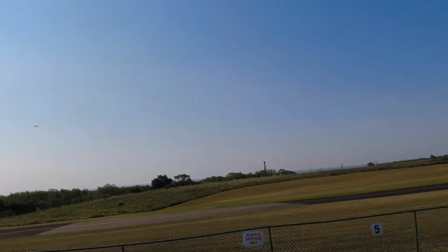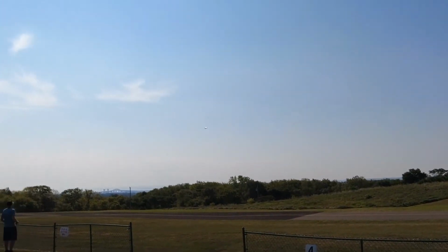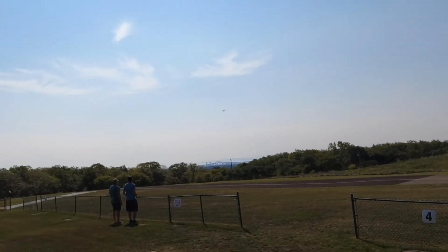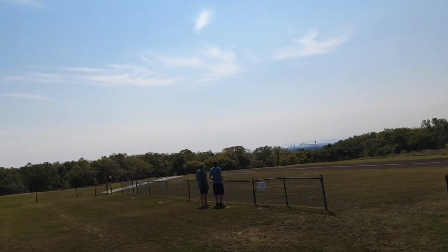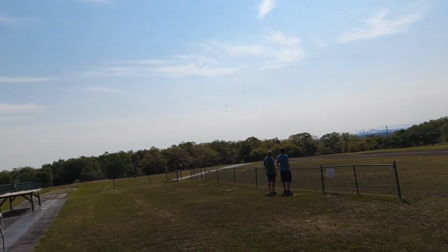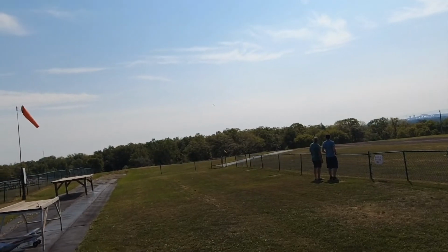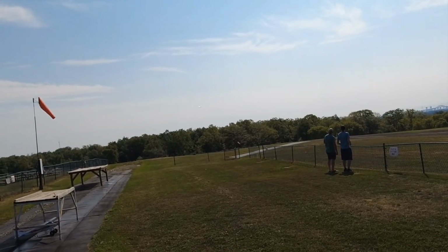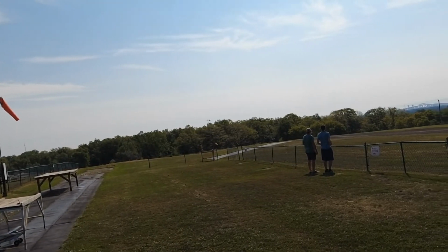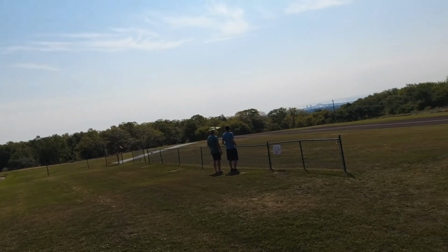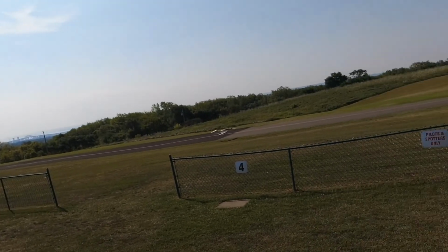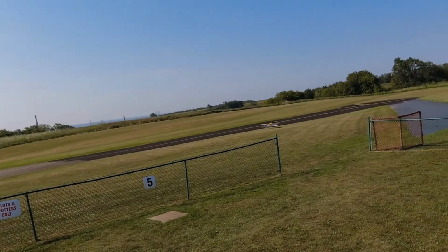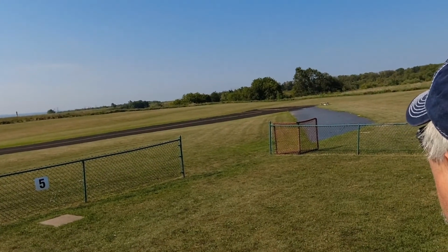Once we get to that specific distance that we're looking for, we can turn base, and that's going to happen right here. And once we turn base on this particular aircraft, I drop the throttle all the way down to idle. You can hear that. And we're on our final approach. Now we just want to bleed the speed off, get the energy levels down, and make sure that our descent rate is going to be pretty well zero. And that's what we're doing when we flare right there and get the plane on the ground.